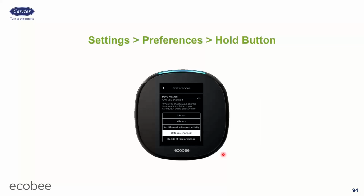So they might keep overriding the stat, and then a few hours later, it goes back to the old set points, and they start getting mad at you because of it. It's probably the way they have this hold action set up. So these are your choices. It could be a 2-hour override, and then it reverts back to the schedule, 4 hours. You can have it stay at the override until the next schedule kicks in.